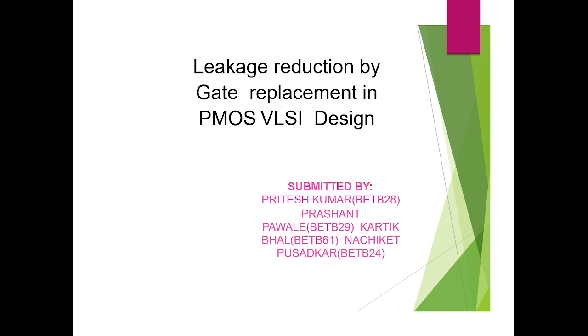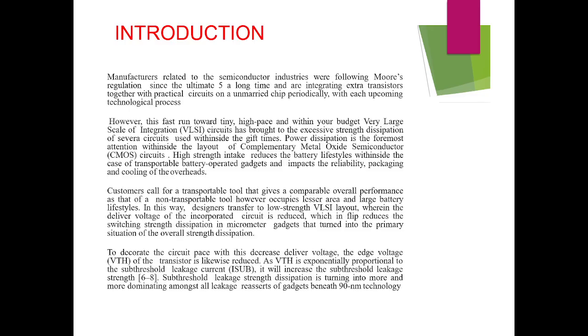So talking about leakage, what is leakage? Leakage current may be responsible for static power dissipation during idle mode, and is increasing dynamically in sub-100 nanometer processes. Sub-threshold leakage rises due to threshold voltage scaling, while gate leakage current increases due to scaling of oxide thickness.